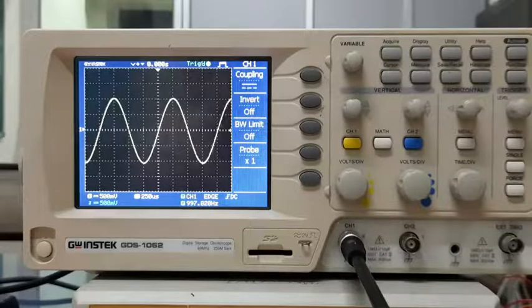So more or less that finishes off how to work with the oscilloscope. There are a few things that I'll repeat so that you can go over them again and again. Know what the signal is in terms of amplitude and time period, and then see that your oscilloscope display is set in the proper range. Know at which input you are giving the signal, channel 1 or channel 2. If it's at channel 1, then set the parameters for channel 1 accordingly.